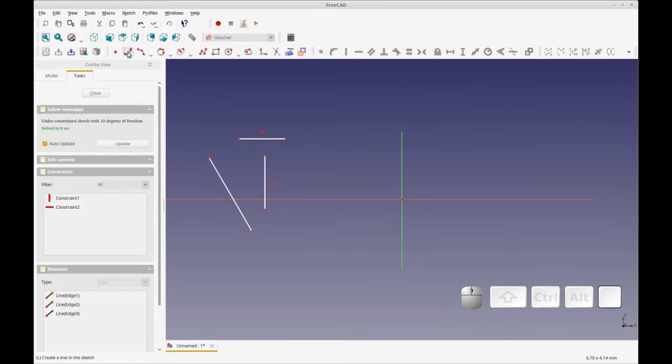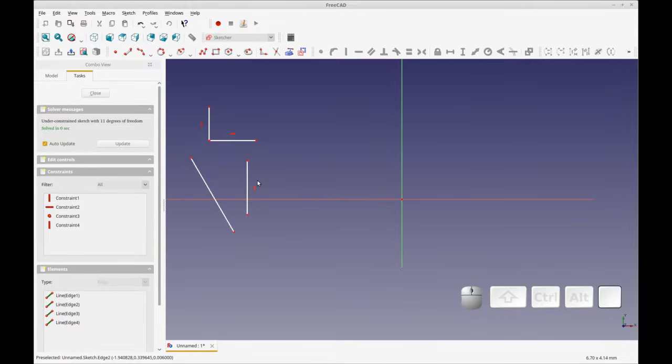The other thing about the line tool, and this will always be true, is that as you're drawing, the various constraints that are available will pop up as you hover over. So that's a tangent constraint. I fix a point onto the object. I call it tangent because that's what it looks like, so that'll lock it to this. This is a coincident constraint, that dot. That means these will be locked, constrained by this corner. So this one has vertically and horizontally constrained lines that are connected at the corner. You can move them just by left clicking or right clicking, which depends on your navigation style.